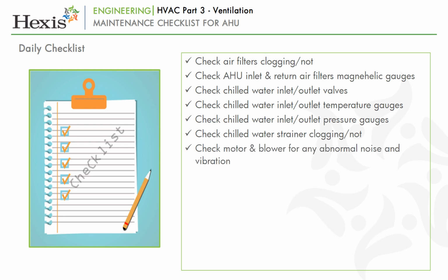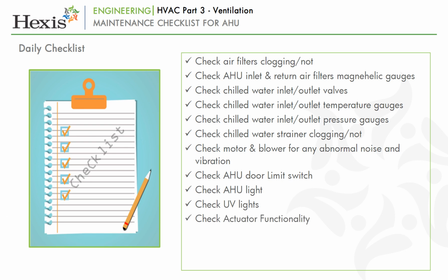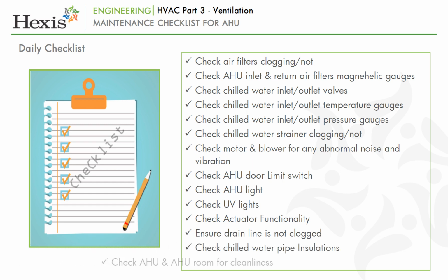Check motor and blower for any abnormal noise and vibration. Check AHU door limit switch. Check AHU light. Check UV lights. Check actuator functionality. Ensure drain line is not clogged. Check chilled water pipe insulations. Check AHU and AHU room for cleanliness.